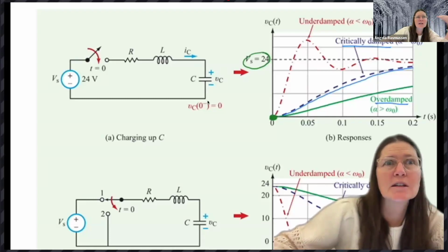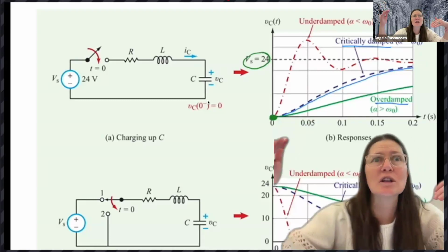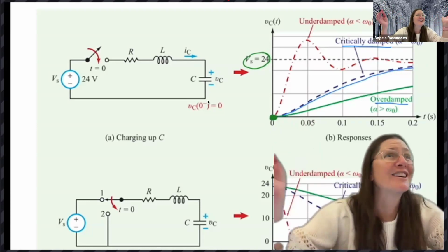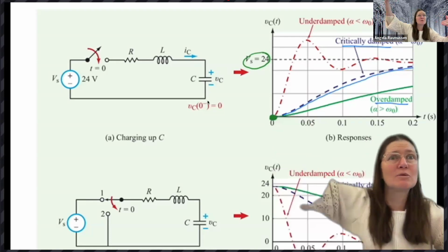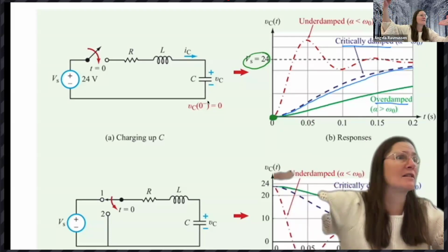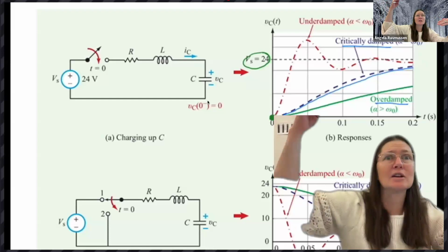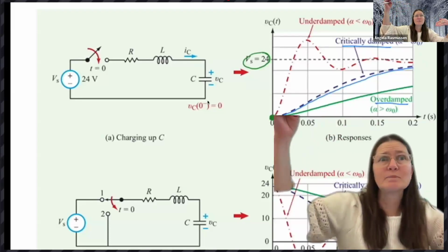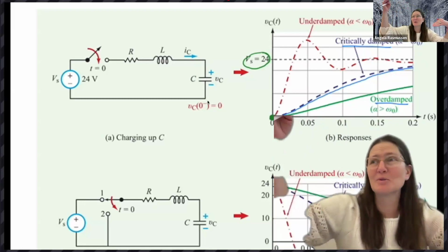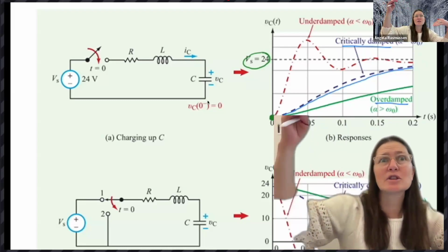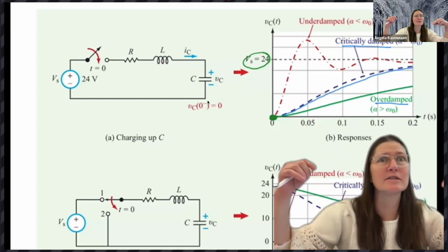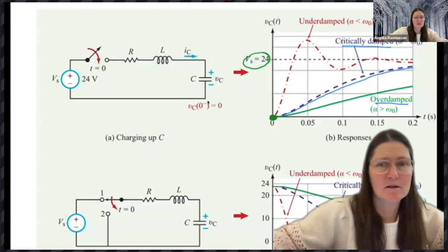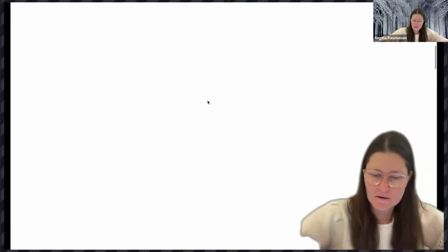So we can find an initial value and an end value just looking at any circuit now with L's and R's, many inductors and capacitances in there. We usually can find an end value and a beginning value just by doing a short for the inductor and an open for the capacitor. What we don't know is what happens in between that time, and that is going to depend on the values of L and C and R. Yes. Go back to the output parallel.